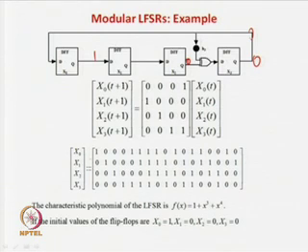So, let this be the seed vector. It is 1, then 0, then 0, and then 0. This is the case. So, after the next iteration what will be the case? We know that this was our control, here is an XOR control, and this control is there. So, obviously this value will come here, this value will come here, and the third value will come here with an XOR condition.